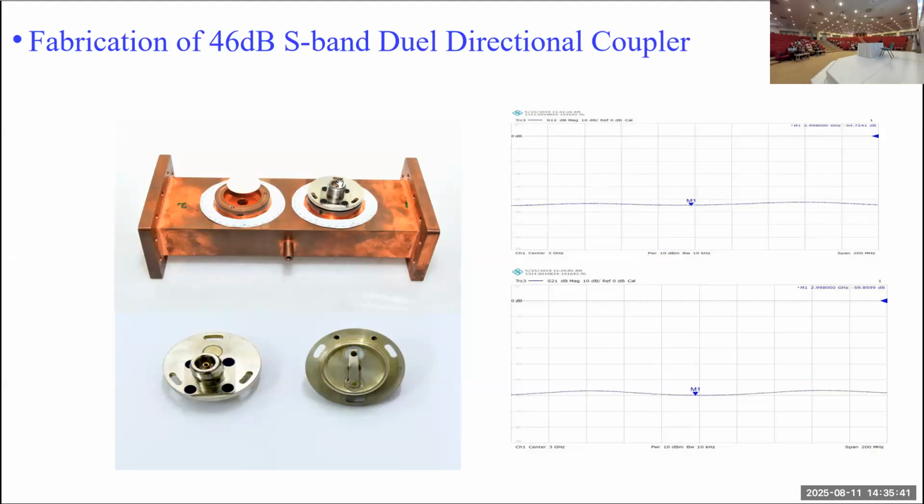If you have 50 dB coupling of your first antenna and you designed it extremely well, and its directivity is 40 dB, then it is a very, very good directional coupler, and very efficiently you can measure the power.